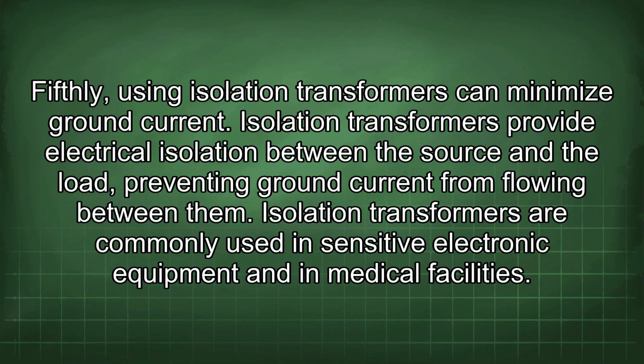Fifthly, using isolation transformers can minimize ground current. Isolation transformers provide electrical isolation between the source and the load, preventing ground current from flowing between them. Isolation transformers are commonly used in sensitive electronic equipment and in medical facilities.